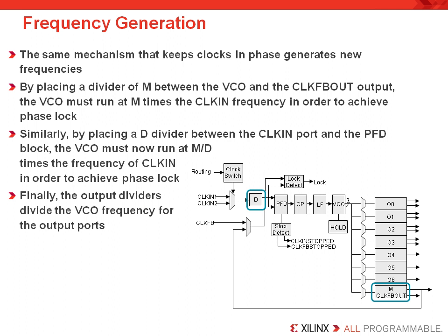The MMCM can also generate new clock frequencies based on the input clock frequency. The output clock frequency is typically measured as a fraction of the M divided by the divisor D times the input clock frequency. Now the range for the values of M and D can be programmed by the user with the use of the architecture wizard. That's via the core generator. But there are also some limits based on the device family. The MMCM or PLL ensures that the desired frequency ratio is exactly maintained. In other words, there will be precisely M output clocks for every D input clocks.